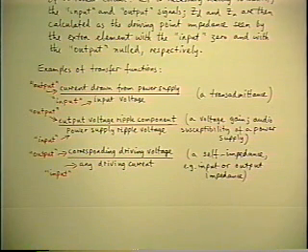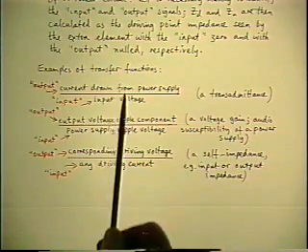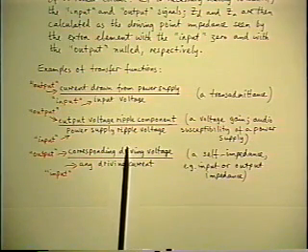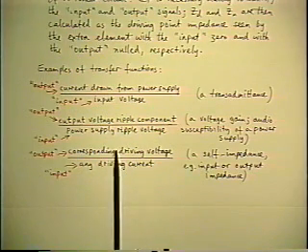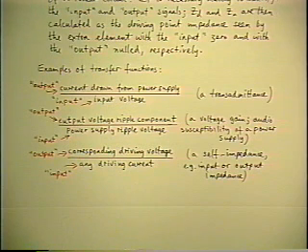These are just a couple of examples to illustrate that the only common thing about all these transfer functions is that the denominator is the independent input and the numerator is some corresponding dependent output. And that's simply a generalized definition of what a transfer function is. And the reason I'm generalizing it at this point is that the extra element theorem can be applied to any transfer function,